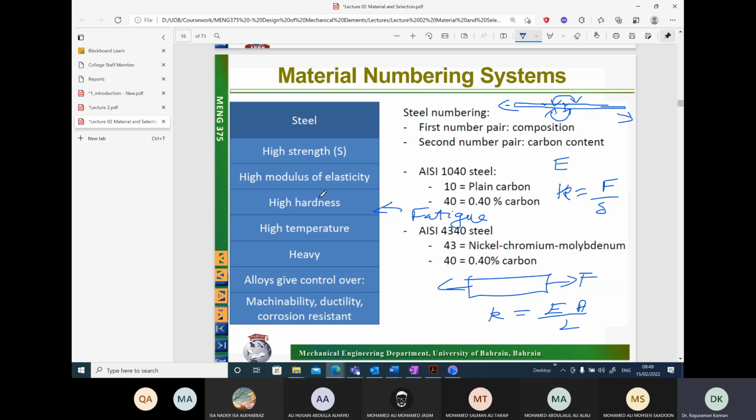If the surface hardness is very large, these cracks will not be forming in the first place, and fatigue cannot happen. Fatigue, or at least the life of the specimen, increases even under cyclic fatigue loads. The higher the hardness, the better.